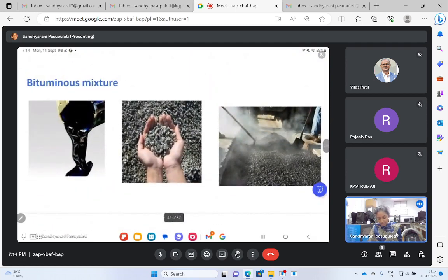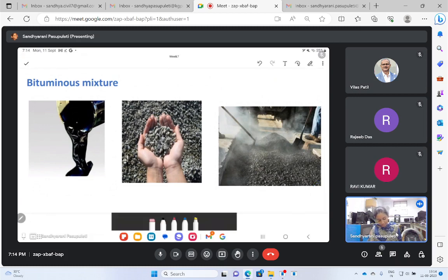So as we have now understood the types of bitumens, especially the modified bitumens, emulsions and cutbacks, let us briefly discuss bituminous mixtures. A mixture is nothing but a combination of bitumen and aggregate; we heat both of them and mix, and we produce the bituminous mixture.